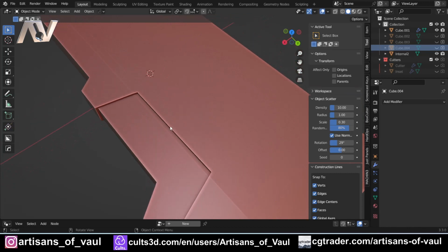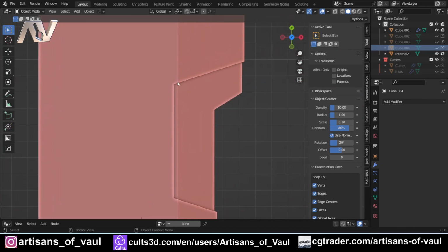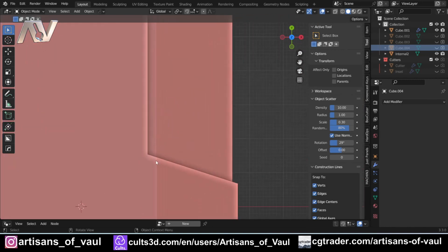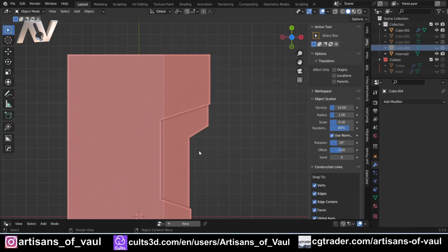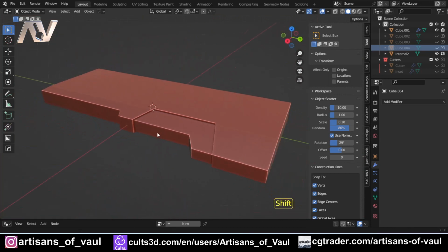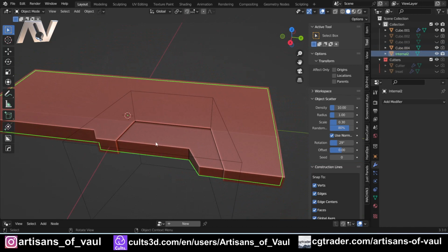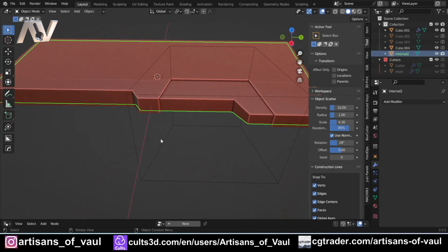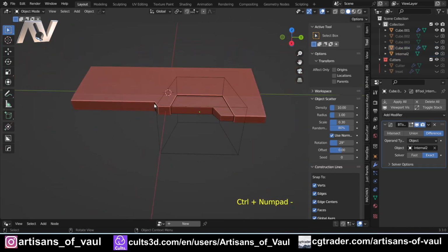You'll also notice, which is really funky, if I come into top view, that this line of where we've got that is much closer to staying put. It has moved a little bit, but not by much. Again, because it's not being scaled towards the origin. And then as before, if we want to do this well, we should not just be leaving that there and booleaning it. What we're going to do is Control and minus and cut that out of the cutter.